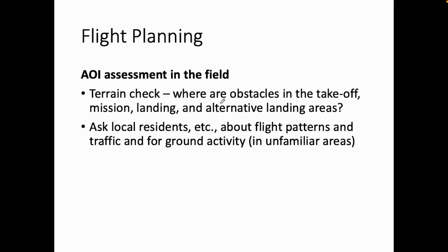So here's an example. I have a DJI Mavic 3E, and it gives you very specific weather conditions for when you can fly. So don't fly in wind speeds 12 meters per second or above. Do not fly at altitudes above 6,000 meters. Don't fly in snow, rain, lightning, fog. Don't fly in below 10 degrees C or above 40 degrees C conditions. And don't fly in specular reflective areas such as water or snow to ensure proper operations of the visual positioning system.